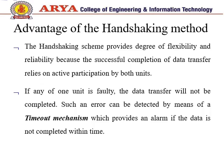Advantage of the handshaking method. The handshaking scheme provides a degree of flexibility and reliability because the successful completion of data transfer relies on active participation by both units. Both units means source and destination. If any one unit is faulty, the data transfer will not be completed. Such an error can be detected by means of a timeout mechanism which provides an alarm if the data transfer is not completed within time.